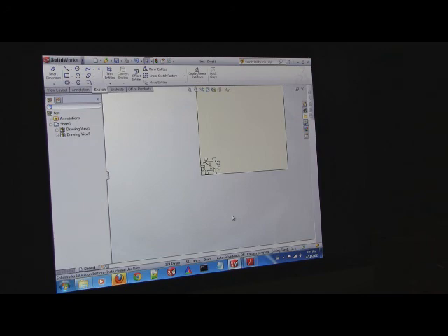Now say this is the part above this. Now it's going to be 3 millimeters, goes to 3.4 millimeters, and that is so that our bolt can go through without touching the sides and interfering. So I understand it seems perfectly random at first when you wonder why that is 2.6 and 2.1. It's because when you add the 0.4, it has actual physical meaning. So it's 2.6, not 2.26, right? 2.6. Okay.